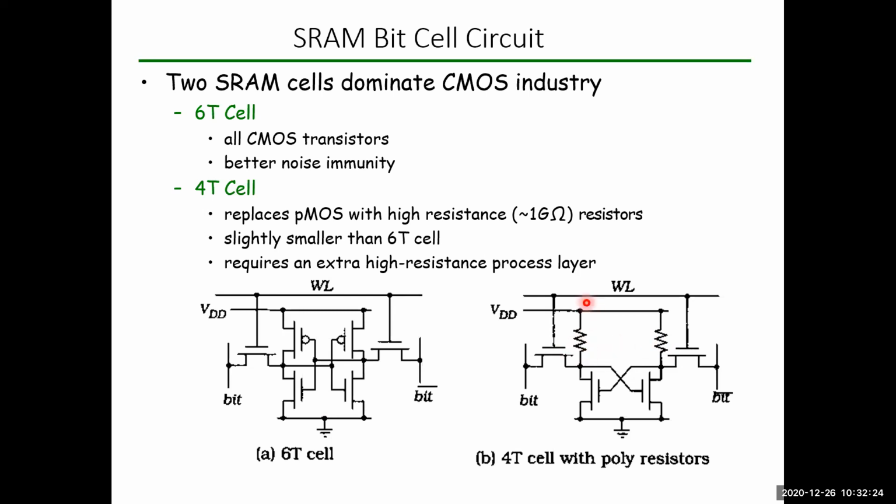And coming to the power consumption, assume that at this particular node I have a 0. Since the other terminal of the resistor is connected to VDD, there is a difference in voltage between this node and that node, so a potential difference has been created. Due to that, a potential gradient takes place, and because of that there will be power dissipation, a loss of charges. That's how the power dissipation takes place over here.